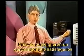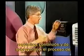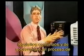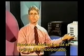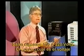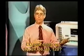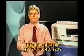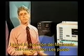Once you've chosen an inverter to meet your continuous and your surge requirements, you are given by the manufacturer's designing process the input DC voltage. It puts out, let's say, 110 or 220 volts AC, but what's the DC voltage that you put in? Is it 12, 24, 36, 48, 120? That comes from the inverter manufacturer's choices.